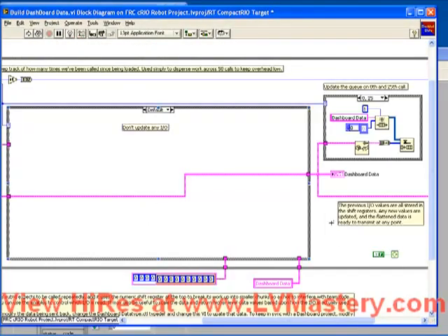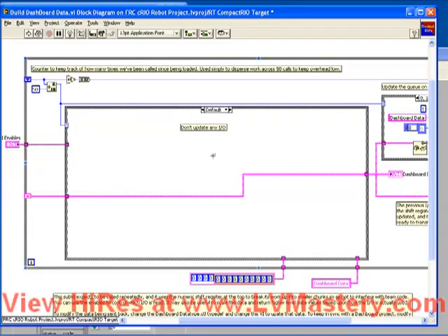So we've done part of the task. We've added the extra data we want into the data type, but we haven't written it anywhere. What we need to do is modify this code by adding a case where we're going to write that data into this shift register. So why don't we duplicate our default case, which by default will take the first available undefined numeric value, which is 16. And in this case, we're going to say update the lifter data.